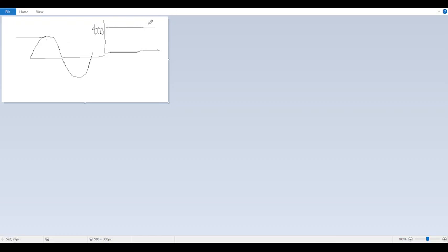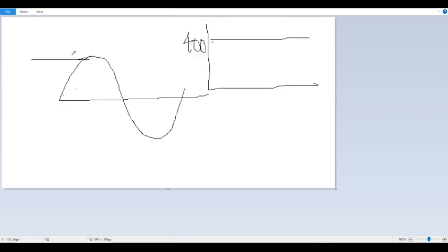Anyway, with this DC waveform coming in, you have to make your MOSFETs vary throughout this, and this is a sine function, right? So the sine at this particular point is basically sine of 0.5 multiplied by pi. If you check that, make your calculator operate in radians. So you say sine 0.5 multiplied by pi. That's actually 1, so it's maximum here. And at pi, it's 0. And at 0, it's 0, right? 0 multiplied by pi, sine 0, is 0. In radians, anyway. I think in degrees it's the same, actually. But in radians, that's what you get.